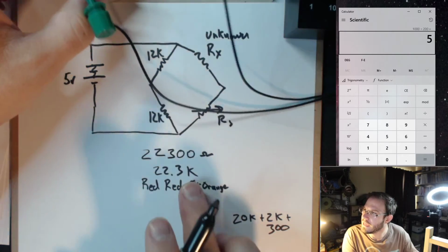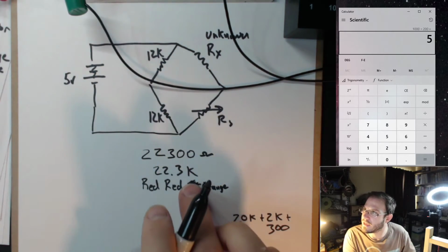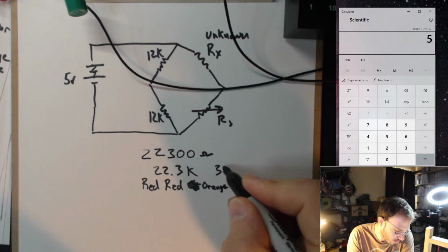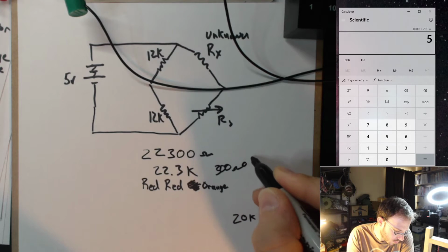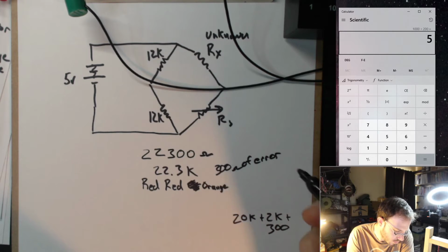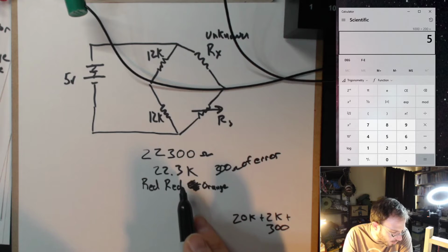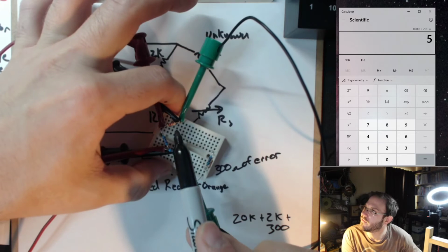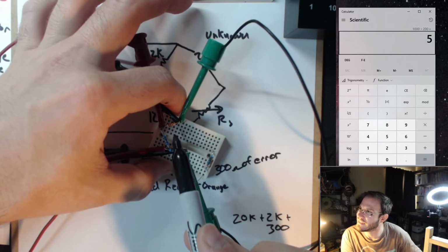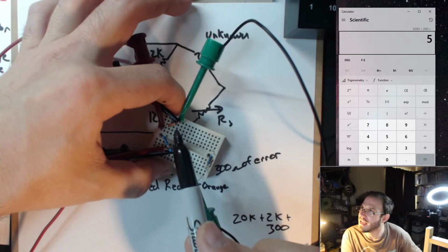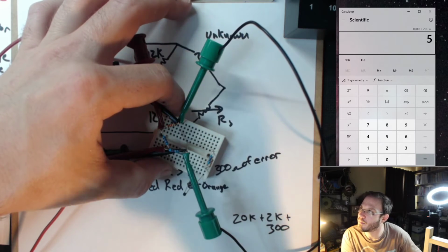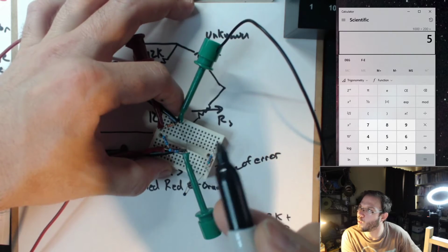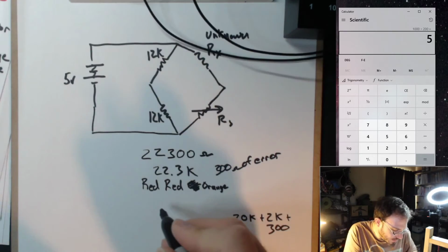So we did measure the correct resistance. This 300 ohms was error. Now, is that tolerable? Yes. Okay. Because this resistor is a 5% accuracy resistance. That means 5% of its intended value plus minus that. Its intended value was red, red, orange, which is 22K.